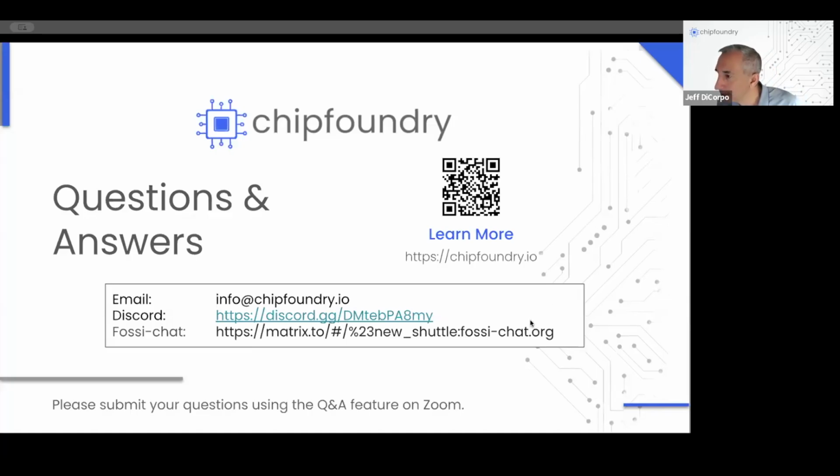Okay, moving on. What is a target node technology? Okay, so if you're not familiar with it, we can probably provide some pointers to this as well. It's called Sky130, and it's basically a 130 nanometer node from SkyWater Technology, which is a foundry in the United States.